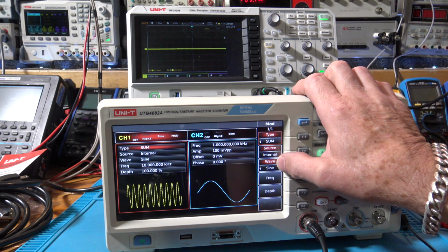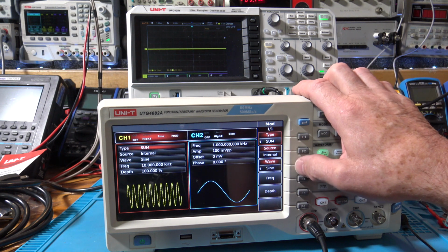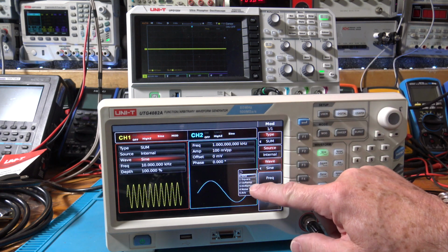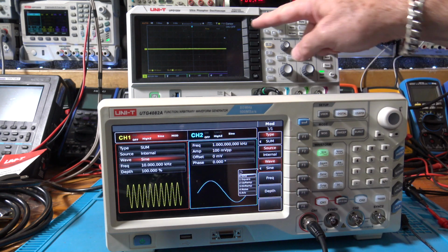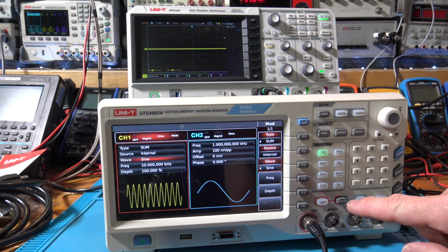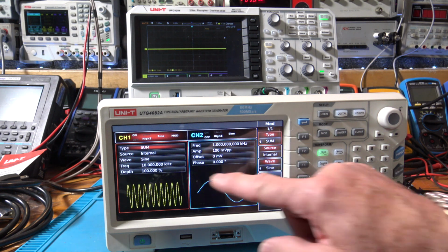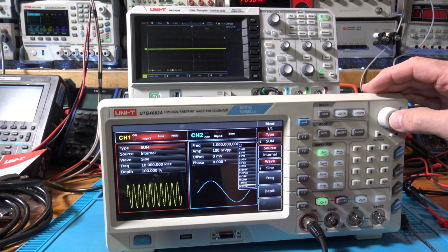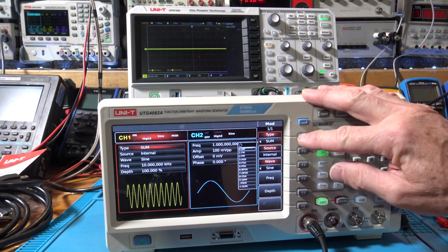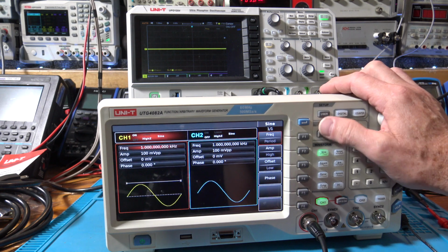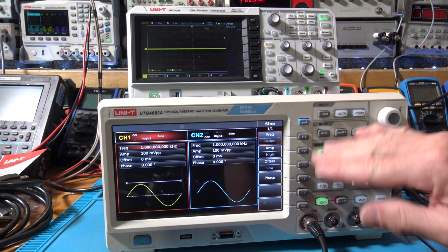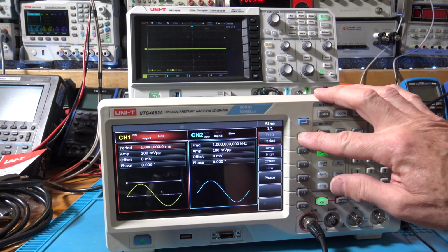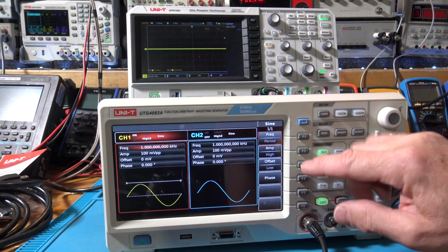And you got source internal or waveform, wave file. And look, let's look at our sine wave, square wave. So here, let's turn on the channel on the output, as a matter of fact. Okay, let's go set this guy up, first of all. Let's turn off the... Okay, so you hit the modulation a couple times and it turns off the... See, one time selects it, another time just gets rid of it. So let's go set up our frequencies.